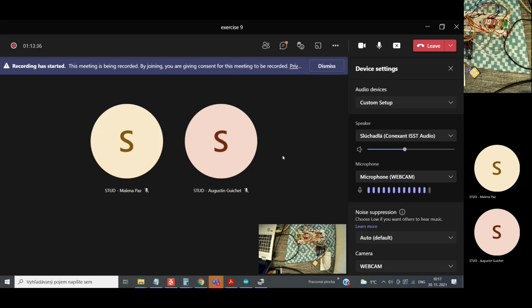The clock is not synchronizing every second with the GPS. When you are making your own project, including GPS, you could, for example, set that the GPS receiver is synchronizing every hour or every day. You should turn it on, for example, for 5 minutes in a day.